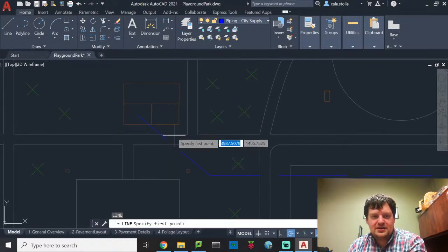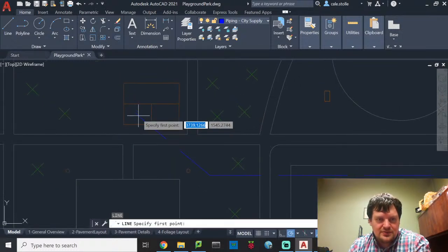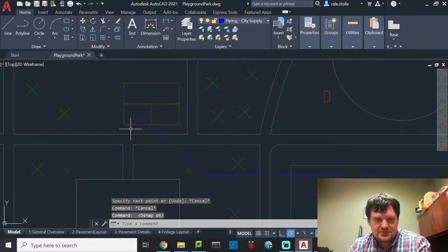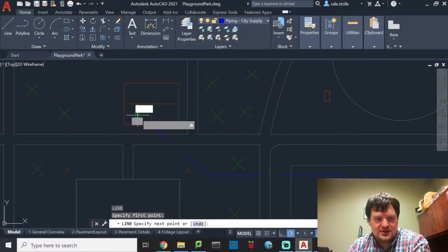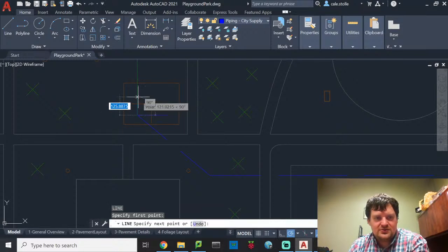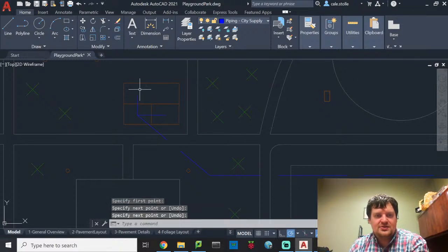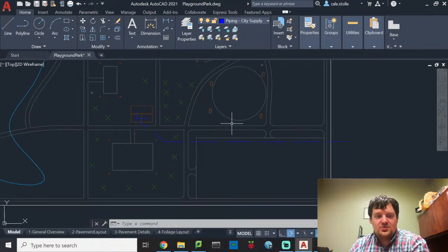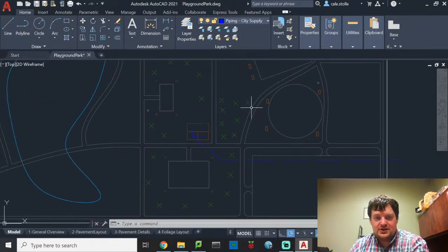I'm now going to draw another line that goes from this location. Oh, I'm going to turn back on my OSnap so I can connect the endpoints of my line. Draw one that goes from here to here, and then we'll draw one that goes from here to here. Okay, so this will allow us to have a utility sink here, and then 2 bathroom fixtures, sinks, toilets. We'll assume that there's some internal routing with this plumbing. We just need an outlet for all three of those. So those are our three flowing outlets. And really this is all that we need to establish that there is piping going into that.